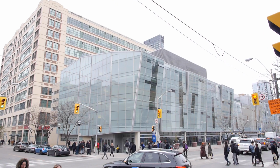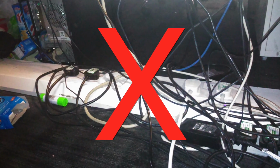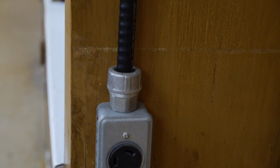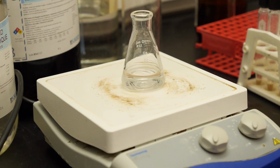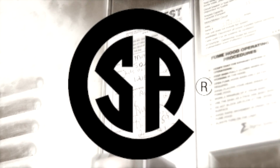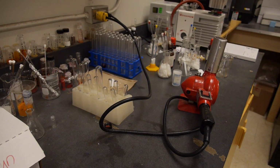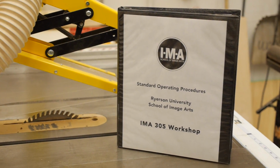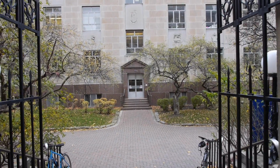Some other key points to mention are to not overload outlets or power bars, report blackened electrical outlets and frayed cords, as well as to replace any malfunctioning electrical equipment. When purchasing equipment or machinery, make sure that all orders meet CSA standards and that all machinery is operated by its guidelines. In most cases, fires are traced back to human error.